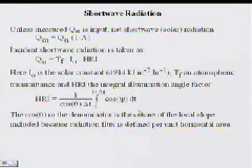Then I've got a slide here that shows the shortwave radiation input. The model actually can take 3 forms of input. If you have measured net shortwave radiation, if you've got a net radiometer out over the study area, then it can bypass all the calculations and you can just take that.